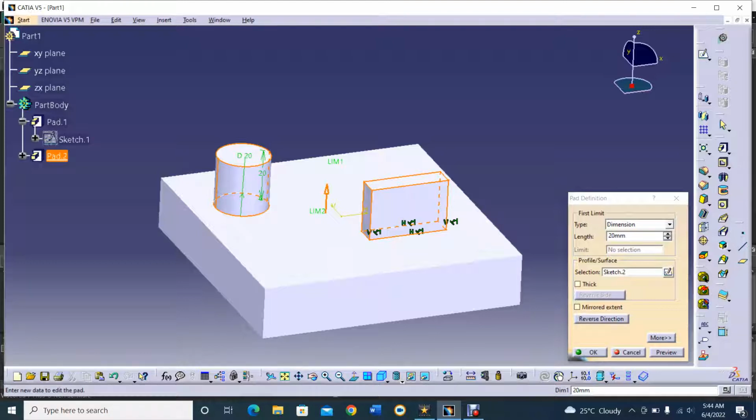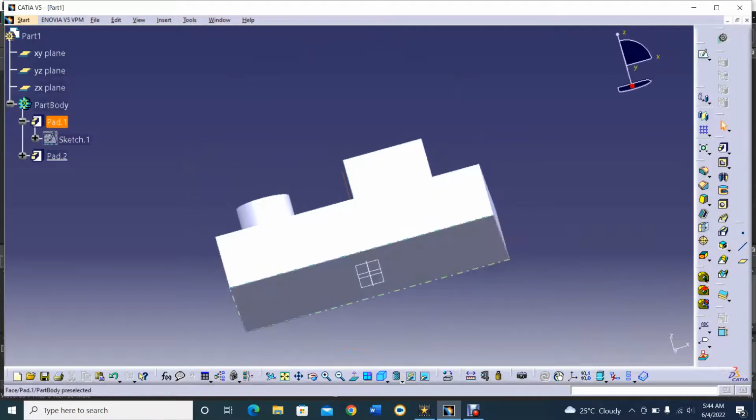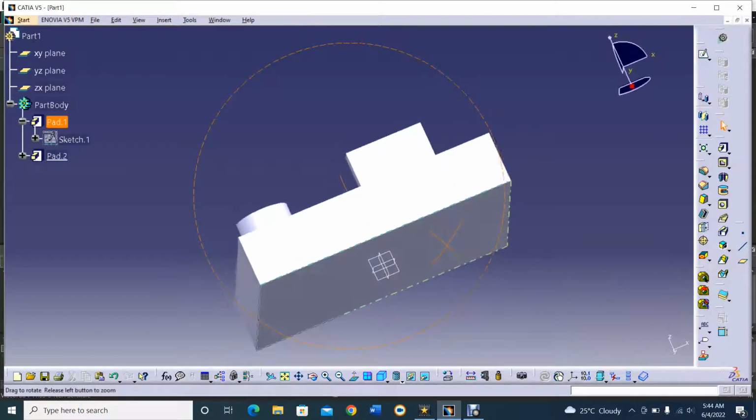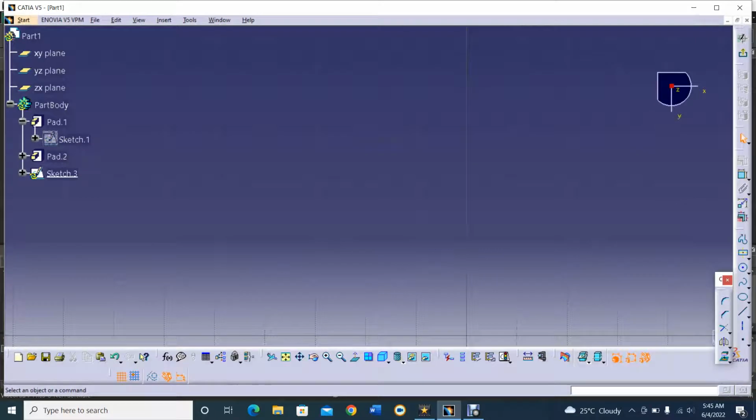Now let's go to use this command. I would like to use the opposite surface for the multipad command. So let's select this sketch plane and go to the sketch toolbar. If the sketch is not available on the screen or it is hidden, go to this tool, fit all in.